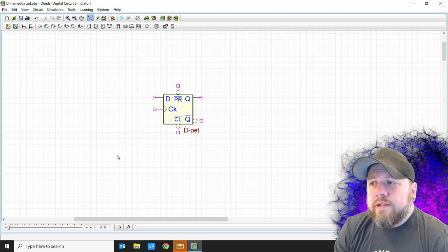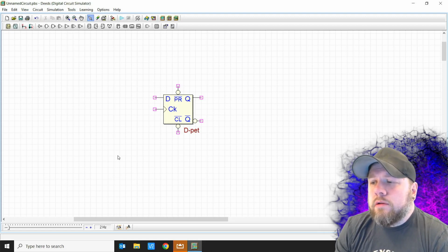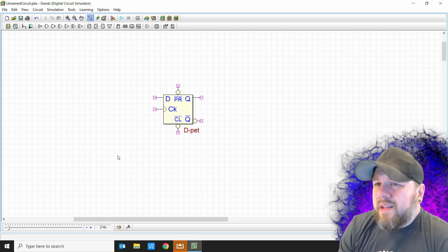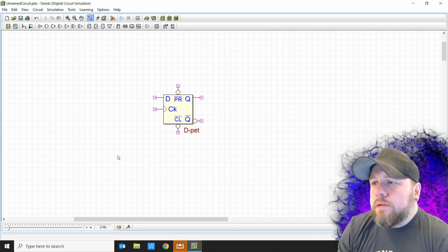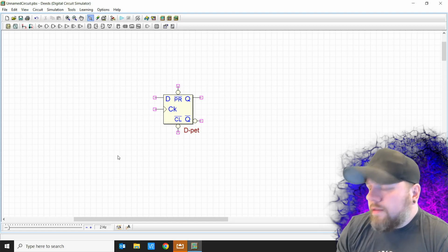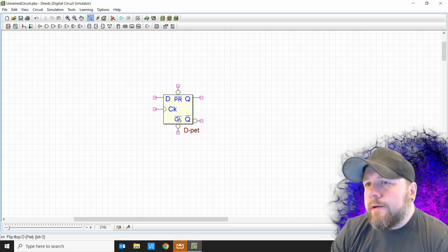And you'll do this a lot if you're going to do any digital design, because you're not going to build the components from scratch. The reason you do it here is because I want you to understand what is actually going on inside of them. Okay, so we've built a flip-flop before. The only thing different about this than what we built is this PR and CL. All right, so PR is a preset and CL is clear. So we can drive this to 1 or we could drive this to 0.